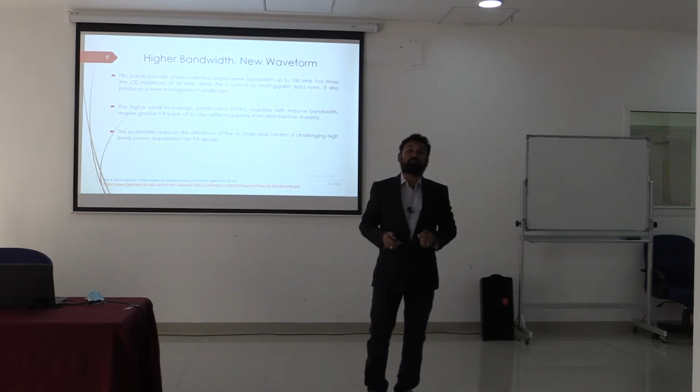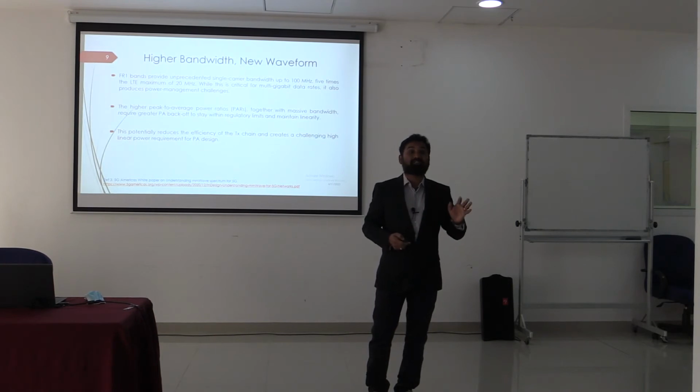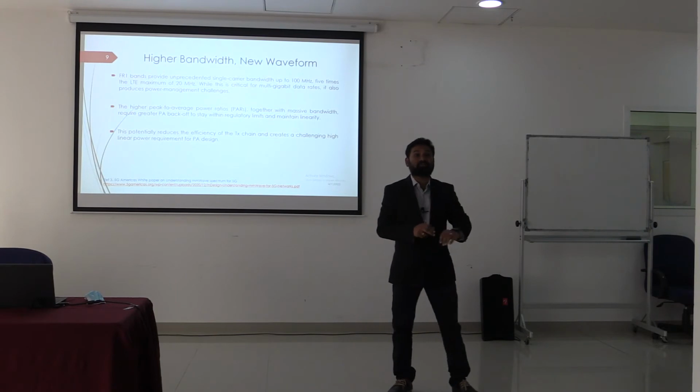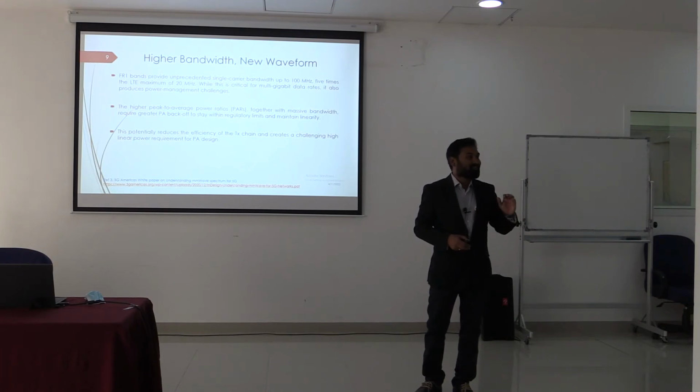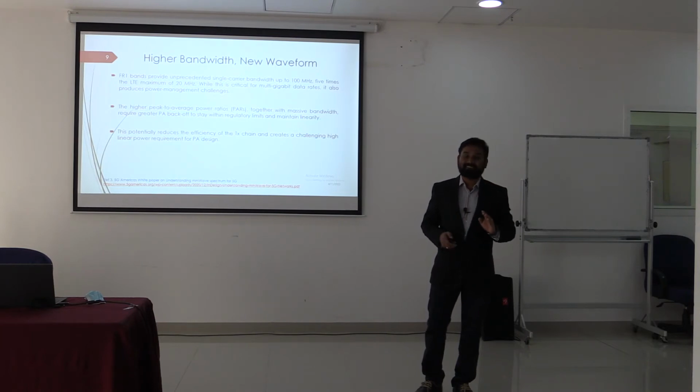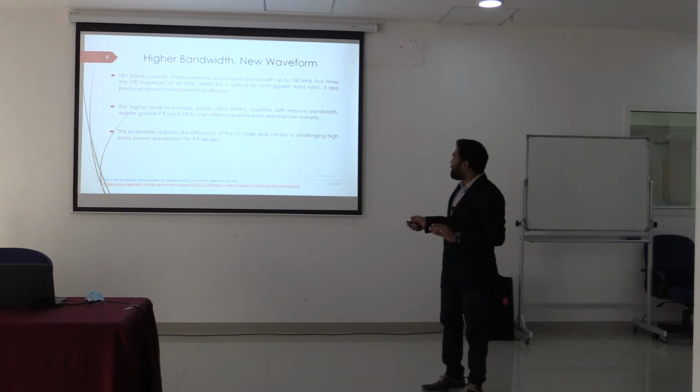Assume it is a low bitrate encoder which encodes at 13 kilobits per second data rate. That is the speech encoder implemented in the 2G, 3G systems. So even in 4G, we can still go with the low bitrate encoders. So if you limit your voice calls with a cutoff frequency of say 3 kilohertz, how many voice calls can we integrate with this 20 megahertz channel?